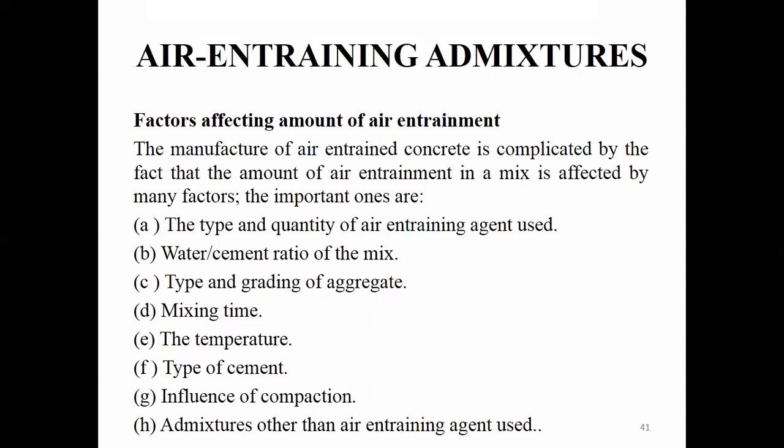This large proportion of the air bubbles will get lost over some time. The quantity of air increased from the lowest fineness modulus to the highest fineness modulus of 2.5. This is also important. Whenever you are adding a higher water cement ratio, air bubbles will be more, and these air bubbles are capable of getting lost over some time. This is also one of the factors affecting the amount of air entrainment in the concrete.